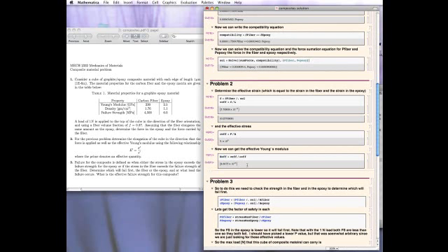And that's it. So with this Young's modulus, we can now treat this material, if you will, as a homogeneous material. Its stiffness is this 89 gigapascals. So now you can just say, well, it's one material, and that's the Young's modulus. If I change the volume fraction, obviously I have to go through this calculation again.